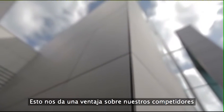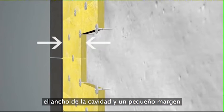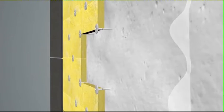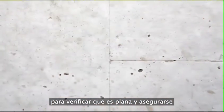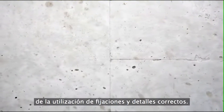Our panels are strong yet light, which reduces the amount of subconstruction needed. This gives us an advantage over some of our competitors. The position of the panel is determined by adding the thickness of insulation to the cavity width and allowing a little extra as a tolerance for uneven walls. Whichever subconstruction is used, the wall should be checked by the installer prior to installation to confirm that it is flat and to ensure that the correct fixings and details are used.